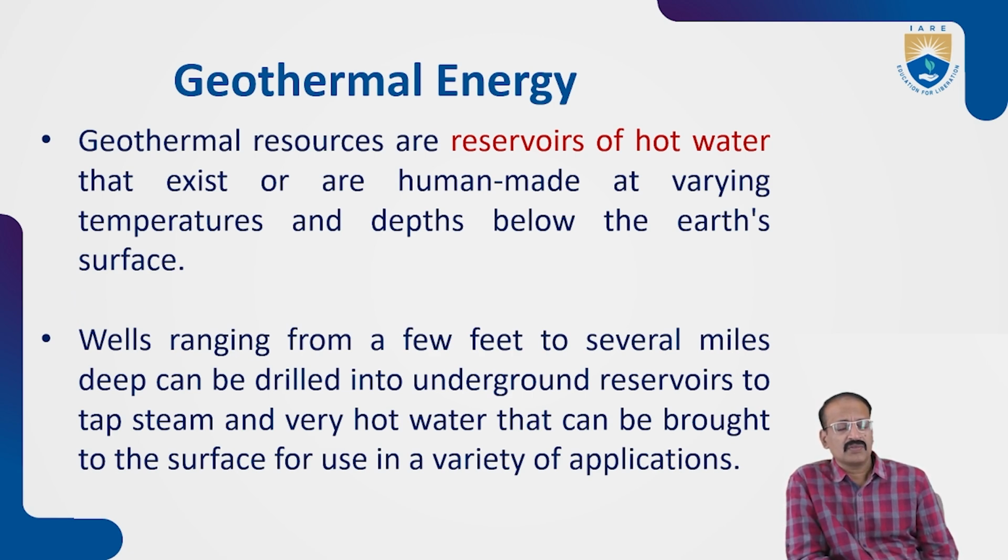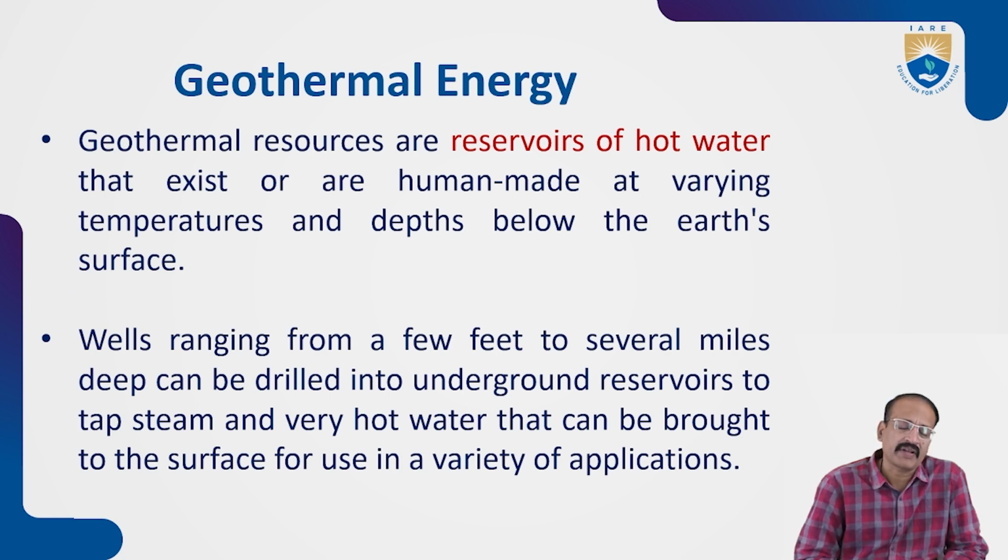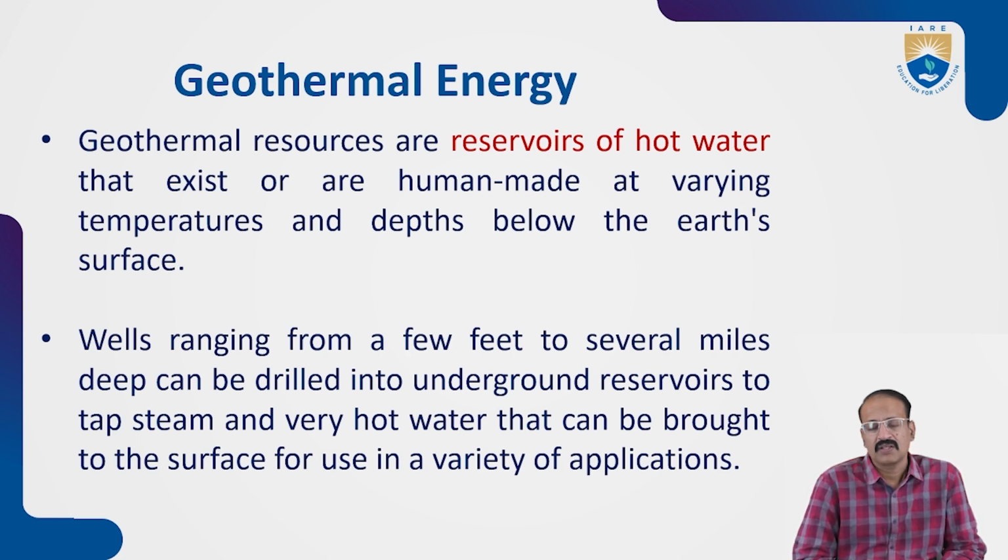If anybody asks why we operate it only to meet the peak load, it is because during the pumping mode we are consuming power again, so there is a cost. So we use it only during the peak load. That was our previous lecture, and it works almost like a renewable energy.